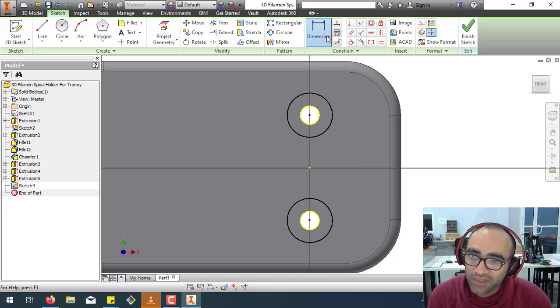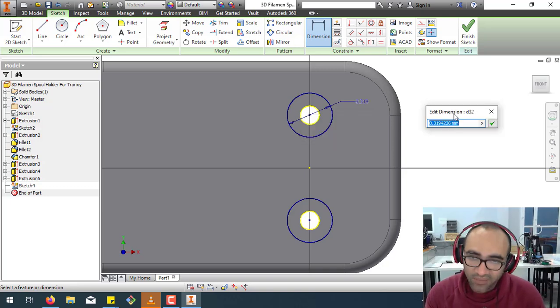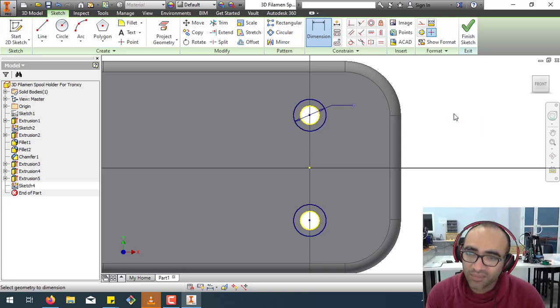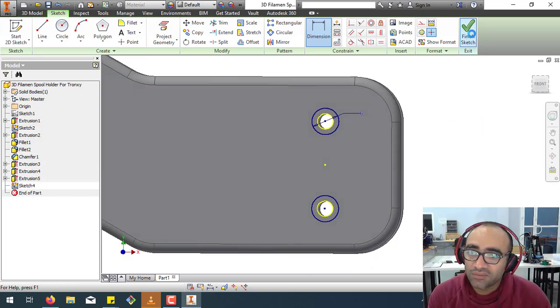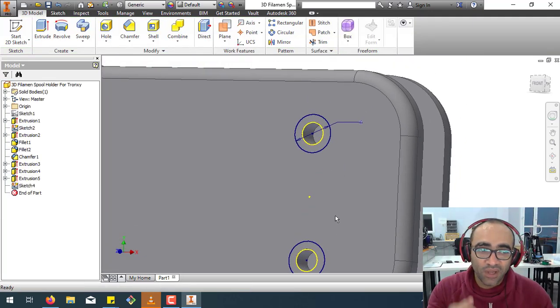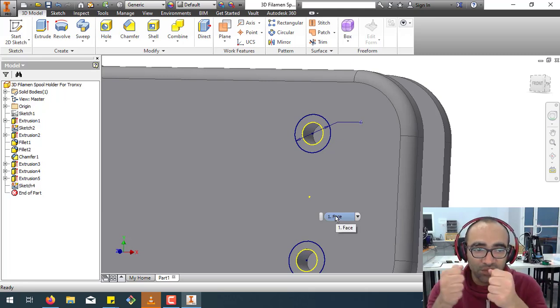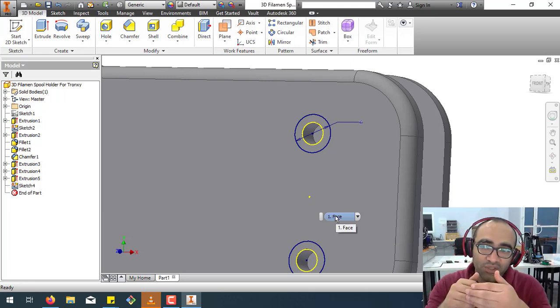and then we say, and usually these 3 mm nuts and bolts, they come 5. So let's say we keep it 6 for safety, because if it's greater, while you are putting the screw inside, it will try to take space, and then it's more likely that your 3D printed part will crack.